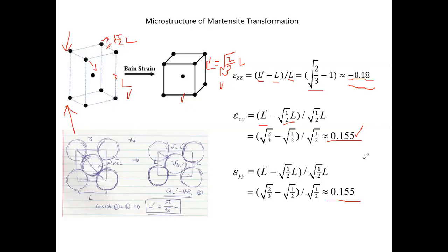We show that there is a clear driving force for you to do the transformation without changing any composition. You can directly induce the transformation from alpha to beta without diffusion, and this allows us to lower the free energy. This is a driving force. And now we also see there's a pathway to do this. It's not a kinetic pathway, but it's a deformation pathway, right?